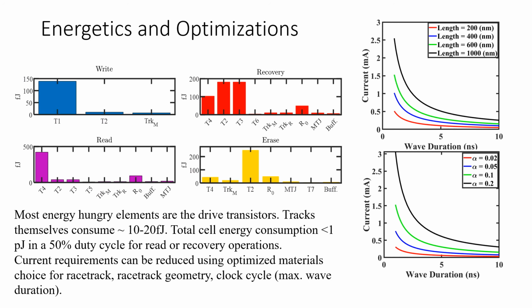Now, if you had to do this using CMOS, you would probably use something like a count-up timer or a Johnson counter, which means that whenever a clock cycle arrives, you count one tick. That's how a Johnson counter works. If you look at the circuit of a Johnson counter, it's built of a shift register. It's a humongous circuit. This has just 8 transistors and 2 racetracks. That's enough, and it's non-volatile. So if you consider all of those propositions, I think it's a very attractive option.